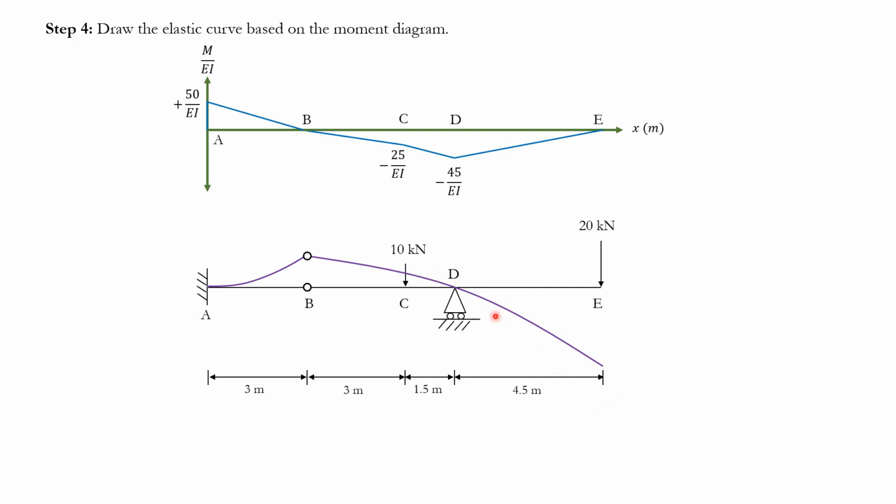Okay, and now this part is pretty obvious. Of course, you're pushing it down, so for this part you would say, okay, of course it's concave down still, so it has to go like this. But you might ask, why is it not going like this? Why not like this? Valid point. The problem here is that the force is large, the lever arm is large, so it's pushing it so much that it cannot go like that. If this kind of support that you see here was here, or maybe closer to the end, or this force was much smaller, then in that case you would be right. Yeah, it would go like this with the dashed line. But that's not what we have.